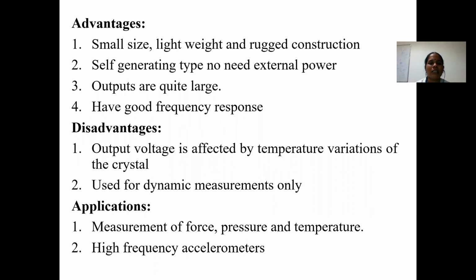Whereas the disadvantage is the output voltage is affected by temperature variation of the crystal. Based on the temperature, the output voltage varies. So for dynamic measurements only it can be used, not for static measurements. The application of it is in the measurement of force, pressure, or temperature, and high frequency accelerometers.